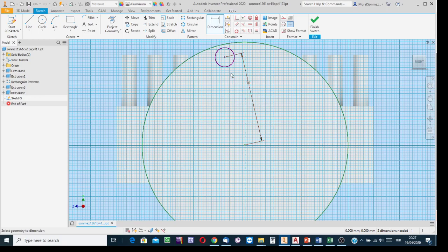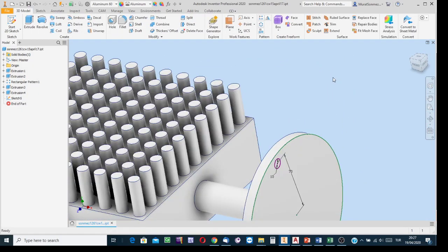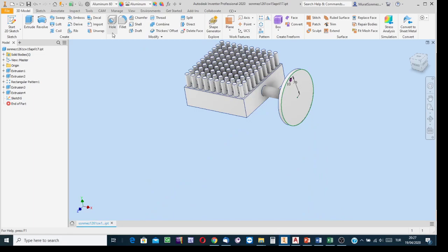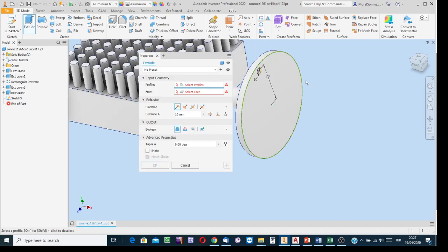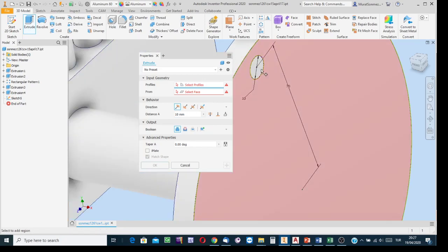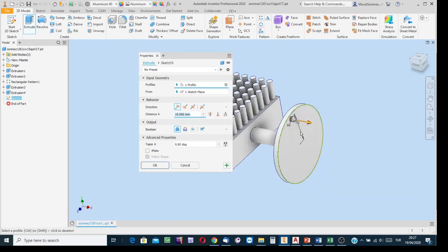Okay, and then after this anchoring stage, indicate the circle and say that its diameter is 10. Finish the sketching stage, and then the rest: first create the model of the element. In this example, it is again a cylindrical extension. Okay, it's just an example. It might be any other, but say it is the profile, so the corresponding feature is a cylinder.